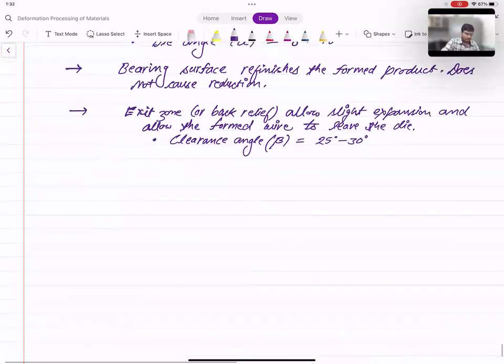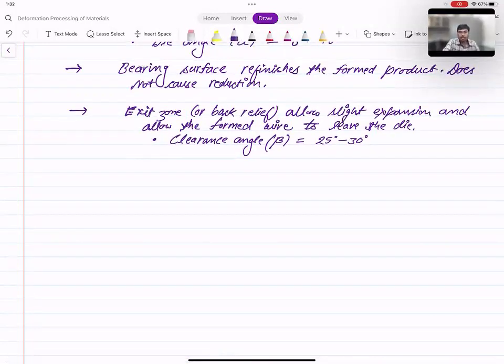Okay. So again, there is an important point that in the wire drawing process, tensile stresses also act along with the compressive and shear stresses which are used in metal forming processes. This we had seen in the very beginning when we were classifying the forming processes, that the wire drawing operation falls into the category of tensile stress type forming operations.